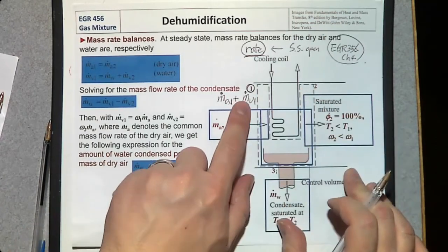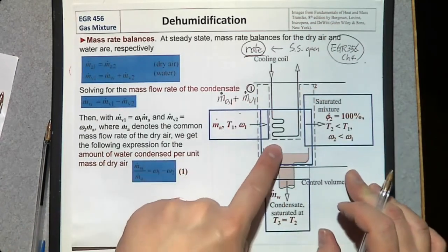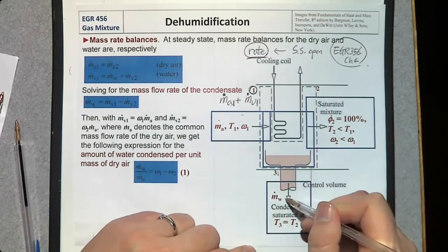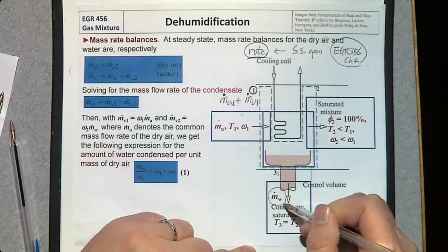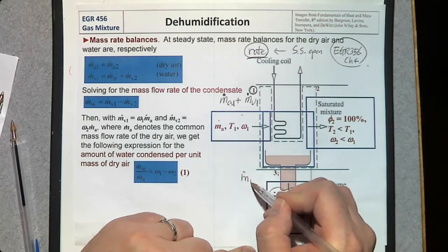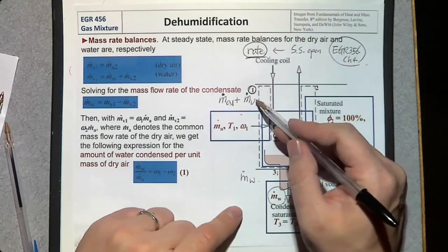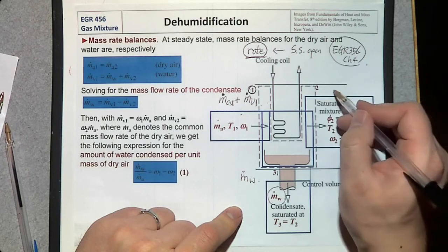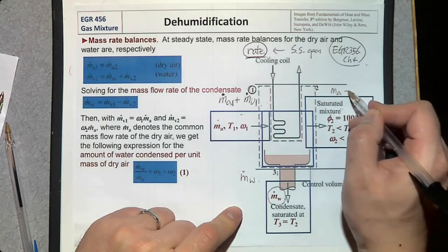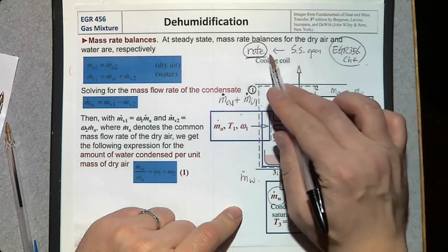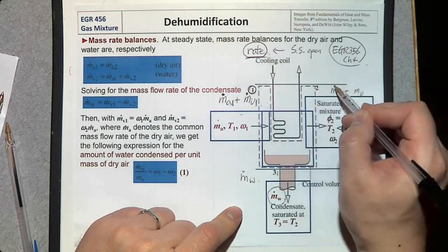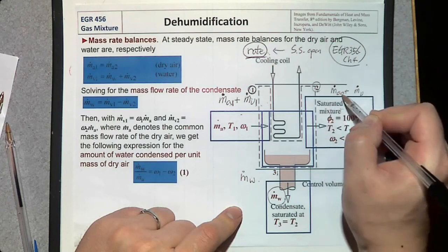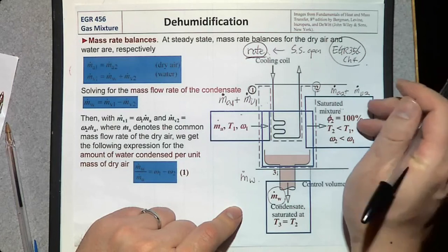And some of the water is going to be removed from the system as condensate, meaning that there's a condensation. And the mass flow rate of condensate is going to be m dot W, which is from m dot V1. And at the exit number 2, we have a moist air, m dot A plus m dot V again. Using the rate form, it's going to be m dot A, m dot V. This is exit number 2. I'm going to add number 2 here, number 2 here.